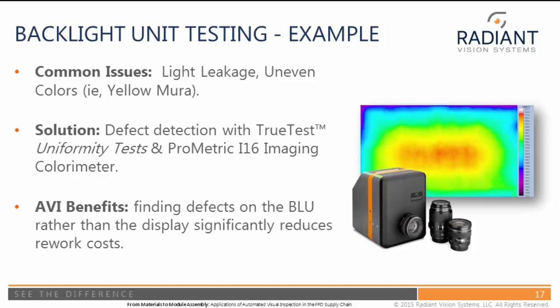However, the resolution of the measurement system doesn't tend to be so critical because the TFT is not present on the device. The reason we're recommending the I16 in this situation is that we have a feature in the software of TrueTest known as multi-channel, which allows us to measure multiple devices simultaneously. And so we have seen applications where we can measure 4 or even more backlight units simultaneously with a single device in a single shot.